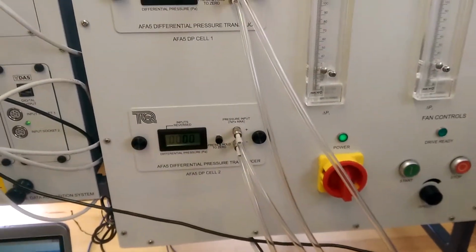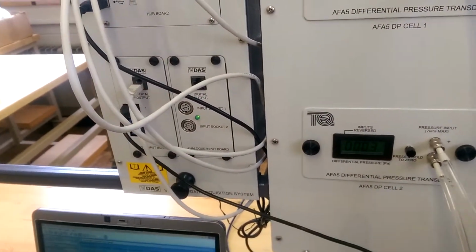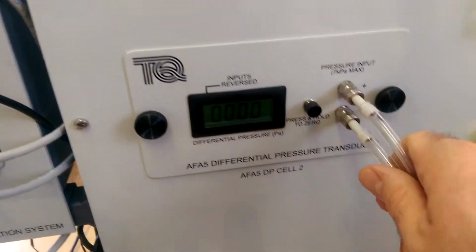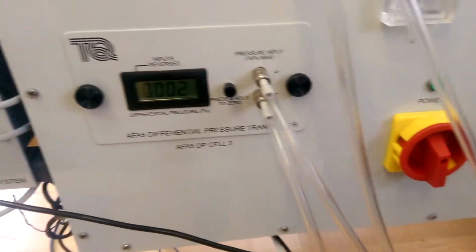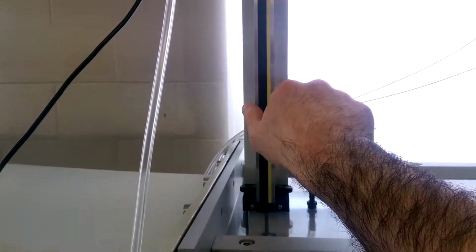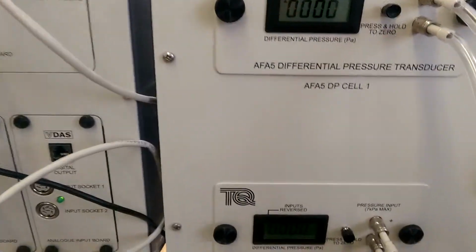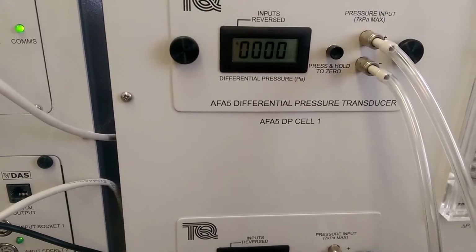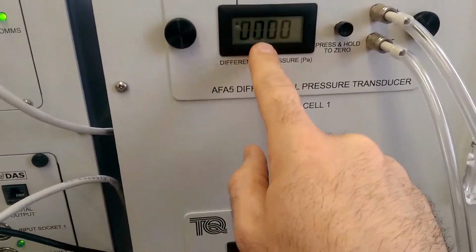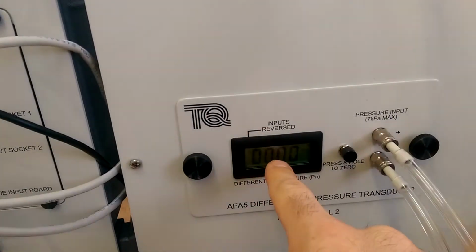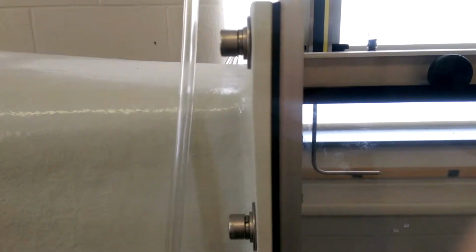Now, the digital manometer on the bottom is connected to the pitot tube that will move vertically up and down. The other pitot tube here is connected to the top manometer. That pitot tube is at a fixed position forward of the cylinder in order to measure the velocity, so this value should be relatively constant during the whole experiment. This digital manometer is measuring the pressure difference across the pitot tube here, which is moving vertically up and down behind the wake that's created by the airflow over the cylinder.